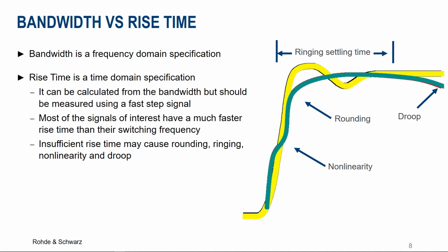A measurement system with insufficient rise time will have step response aberrations as shown in this example. The question then becomes, are those aberrations caused by the probe or the half-bridge? Also, measurement vendors will peak a probe's response to improve the performance, causing overshoot and affecting the settling time.